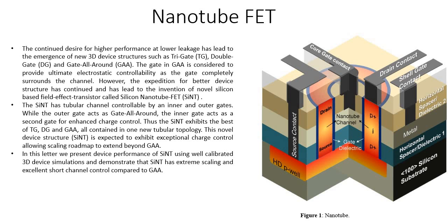So why are we moving to the nanotube? In the previous video I discussed nanowire. Now nanowires are facing problems when they are being scaled down. The problem is that a higher number of short channel effects are coming, very high leakage current is coming, very high drain induced barrier lowering is coming, gate induced drain leakage is coming.